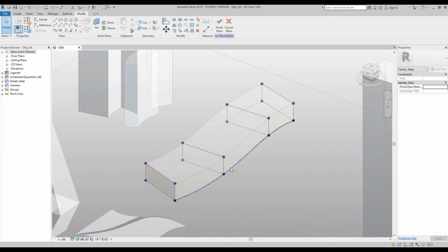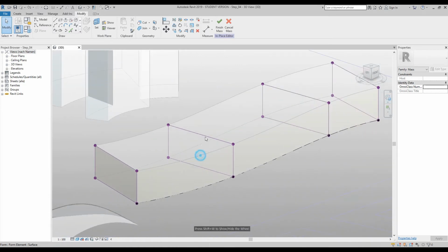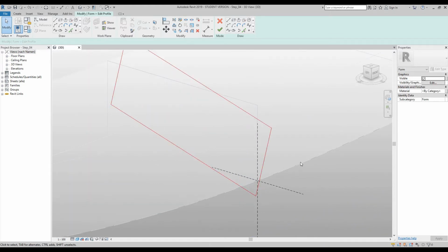And to jazz up our design just a little bit more, we're going to edit these profiles. So if we just get a good view, and if we tab on that rectangle, you can see right at the top, edit profile. User interface goes green, and you can see our red lines. Now if we select the whole thing and use the rotate tool, and if we press spacebar, and if we place it pretty much about 1/3 in from the right, and then rotate it at the other end, this end point here, if we go up maybe about 15 degrees, you can type in 15 on your keyboard, there you go, that's done. And what we're going to do is cut off the bottom edge, because you can see it now goes past our pivot point.